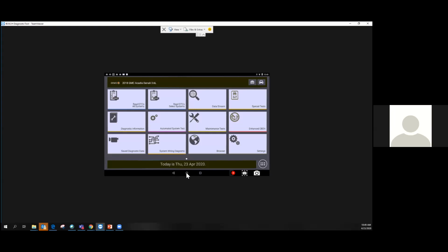Well, that's where I'm going to jump into Tech Advisor, right? The tool's not going to do me much good because, unless I manually enter it, put it in demo mode, because you're right, that ECU is not live. It's not going to identify the vehicle. That really is the hub of everything, right? And typically that gateway module is only going to be turned on with the ignition on.